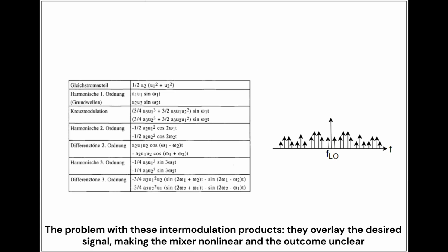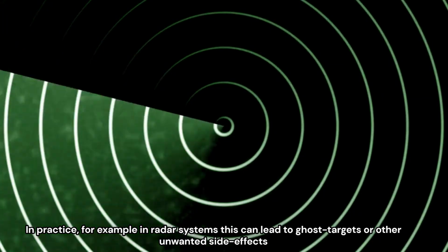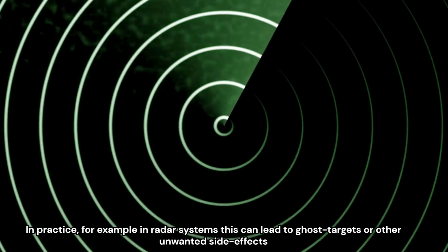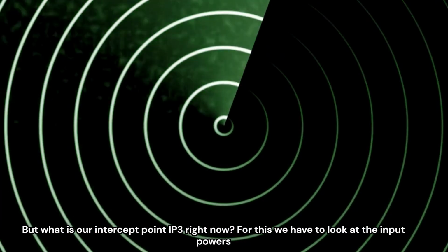The problem with these intermodulation products is that they overlay the desired signals, making the mixer nonlinear and the outcome unclear. In practice, for example in radar systems, this can lead to ghost targets or other unwanted side effects. But what is our intercept point right now?